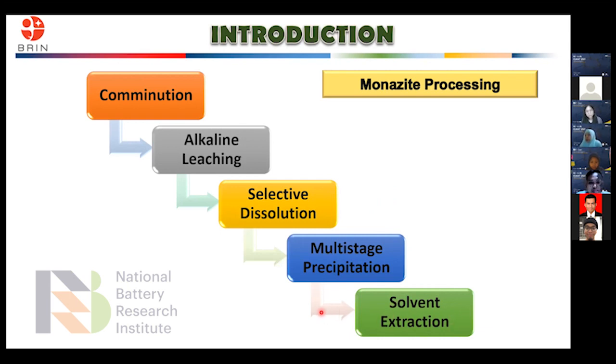Solvent extraction is a process of separating a component from a mixture based on a distribution process of two immiscible solvents, namely the aqueous phase and the organic phase. The separation of uranium from the feed solution, which still contains various elements, is conducted by using a selective solvent organic phase for uranium. The organic solvent or extractant used in this research is trioctylamine, or TOA, mixed with kerosene and isodecanol.